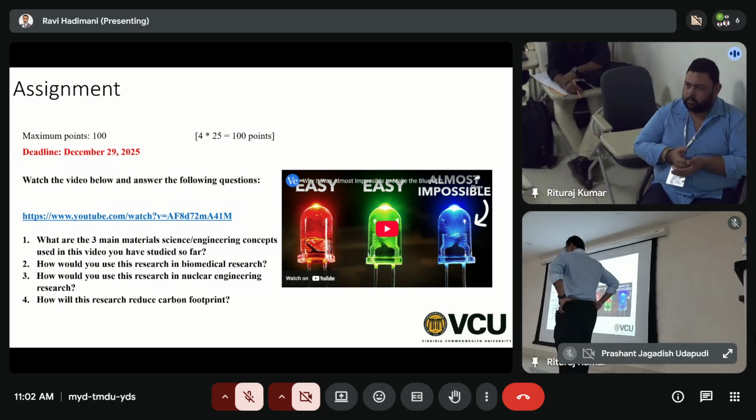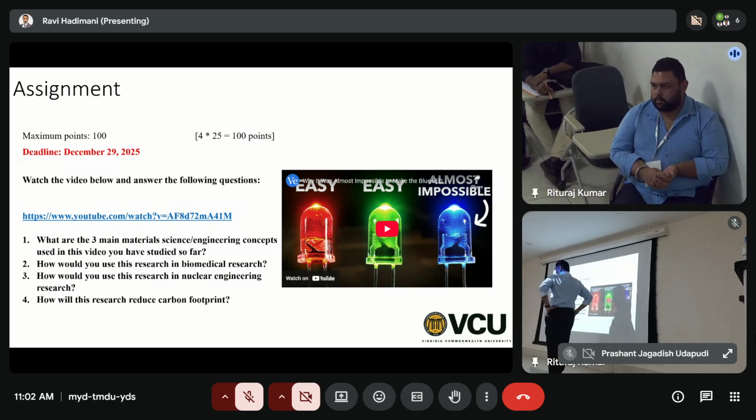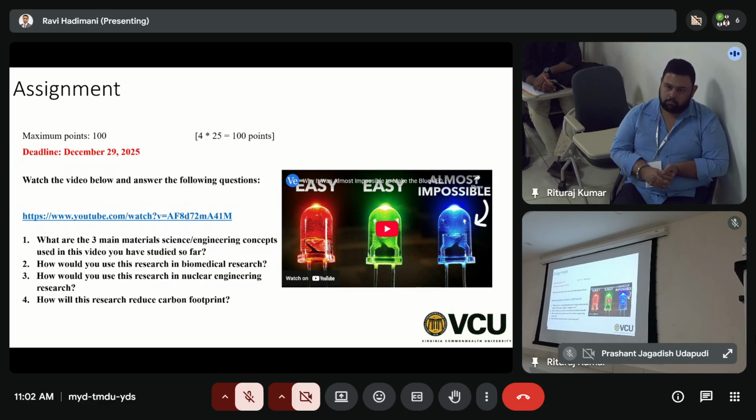Okay, so the substrate, right? So there are two requirements. One is the substrate itself. What kind of substrate? The first slide I showed, atomic radii. You have to match the atomic radii of the substrate with the atomic radii of the material that you are depositing. Okay, if there is a mismatch, then you have internal stresses that will change the property of the deposited film.